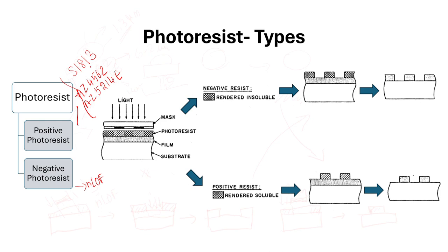Here we have these last two digits, right? That will tell us how thick the photoresist is. Say if we are having S1813, if we coat the photoresist as per the standard parameters given in the data sheet of the photoresist, there is a certain amount of time for which we have to spin the photoresist, and a certain speed at which it should be spun.